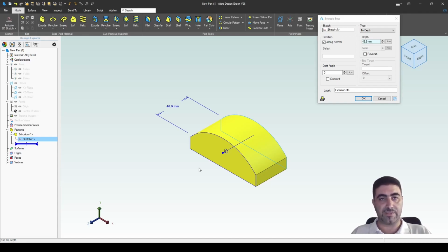It is the sum of points that, when projected along the normal of the plane that we sketched on, okay, that projection falls into the boundaries of our sketch. Okay, that is one of the properties it has to have. The second one is defined here, right? It's the depth or dimension. You might see this being called in another CAD system.